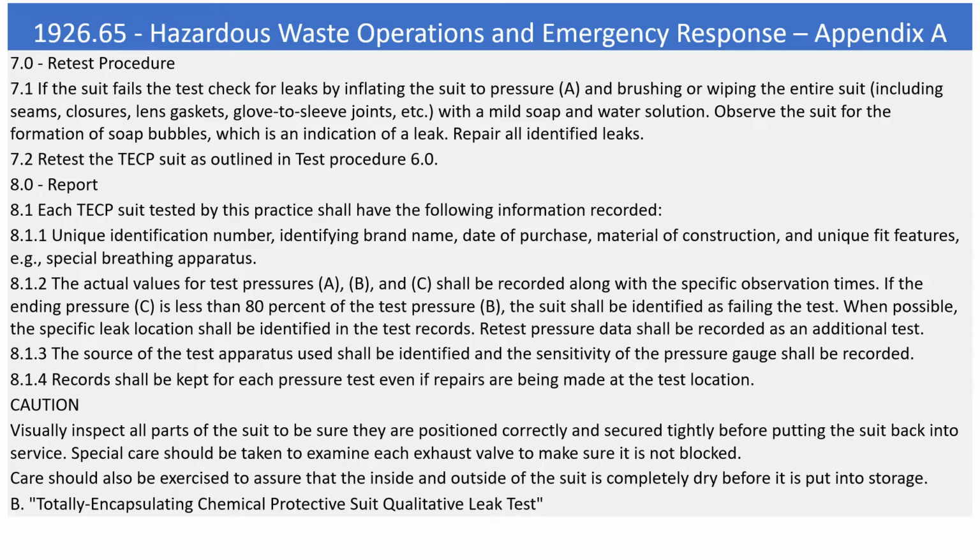8.0. Report. 8.1. Each TECP suit tested by this practice shall have the following information recorded. 8.1.1. Unique identification number, identifying brand name, date of purchase, material of construction, and unique fit features, e.g., special breathing apparatus.